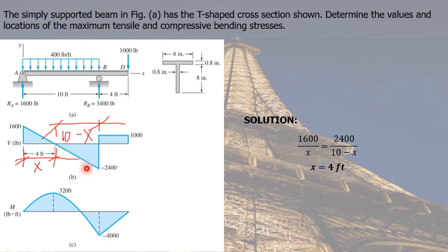Again, this is linear in shear. It then becomes a parabolic curve in the moment diagram. But does it concave downward or upward? Again, at this point, the slope of the parabolic curve should be 0. And at point B, the slope of the parabolic curve should be negative. For that to be possible, the parabolic curve should concave downwards.